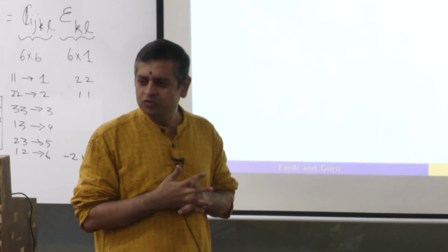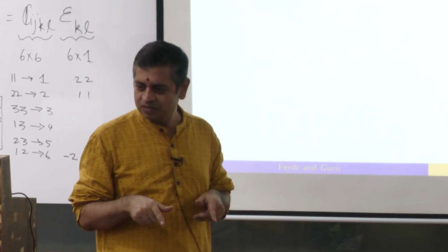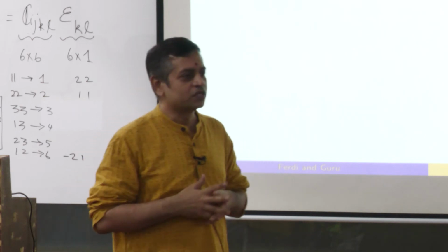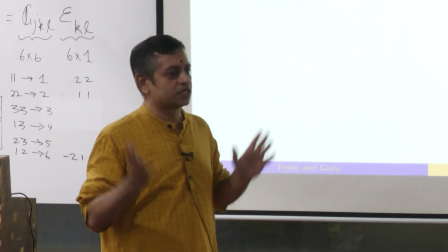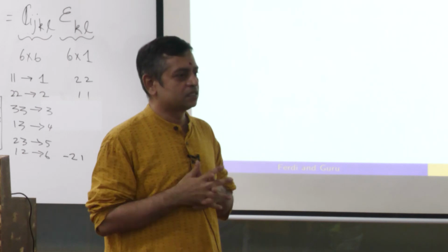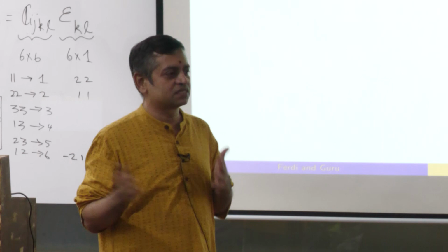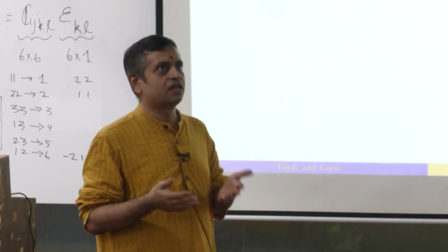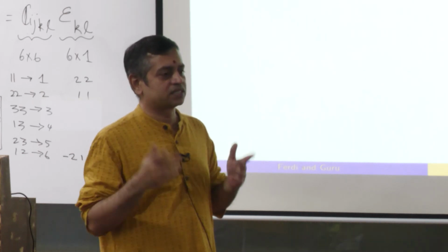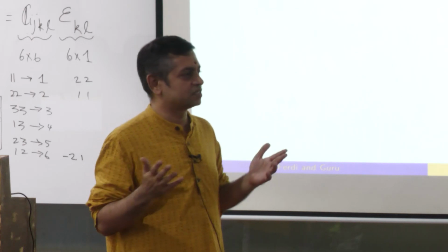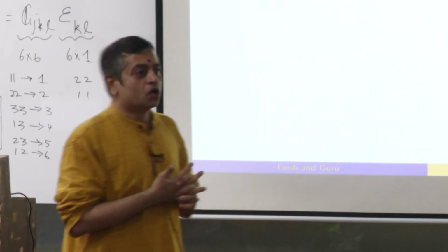That is the Zener anisotropy parameter, which tells you that if it is greater than 1, the 1 0 0 directions, or if it is less than 1, the 1 1 1 directions will be softer in a cubic system, and so on. Okay. It is interesting.